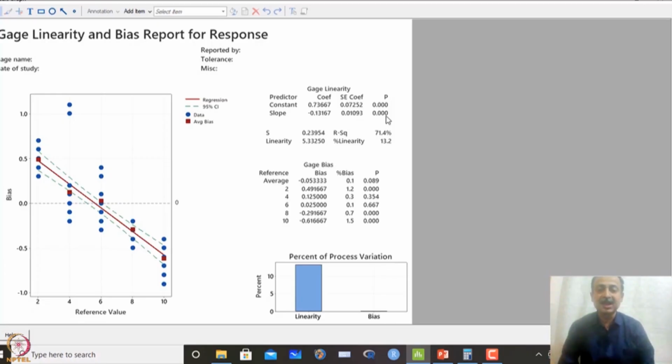That is why we are using process variability measures over here, and we are finding out the percentage, how much the linearity or this shift deviation is with respect to the process deviation. So, these measures can be taken based on the industry standards you are following in your industry. So, that way we can express linearity.